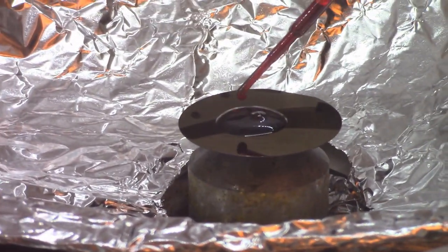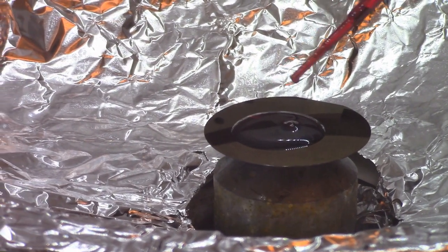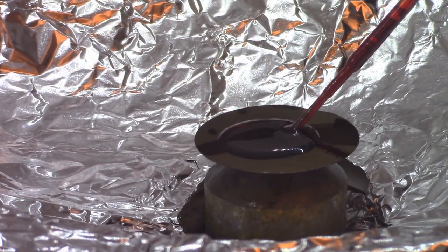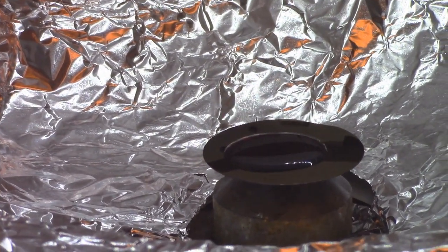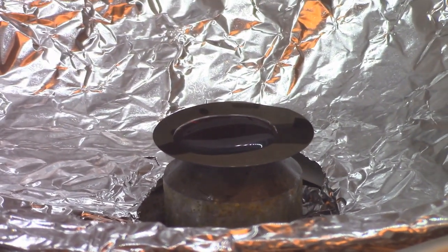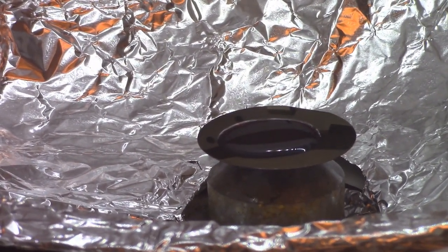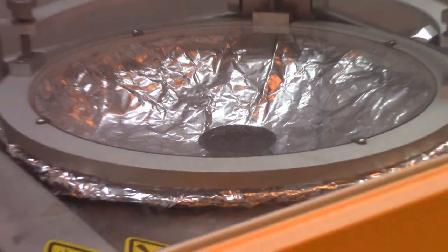Any bubbles that remain during the spin coating process can actually create areas with non-uniformity of the photoresist, so we can make sure that we suck away all the bubbles by using a reverse dispense action. It's also important to not waste too much photoresist, so we can dispense the photoresist on just 2/3 of the area of the wafer. Once it is dispensed, we can go ahead and start spin coating.